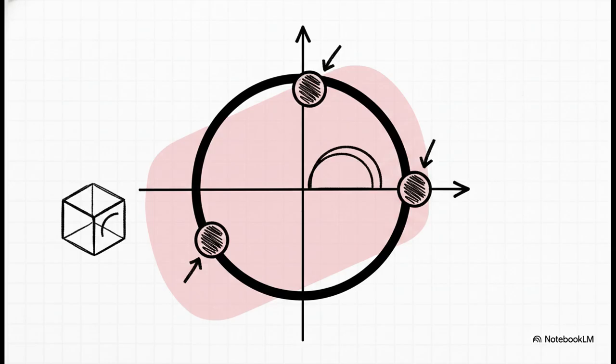But you've got to remember one absolutely critical rule. Angles on Mohr's circle are double the physical angles. So if your principal plane is 17 degrees away in the real world, it's going to be 34 degrees away on your drawn circle. Keep that straight and you're absolutely golden.